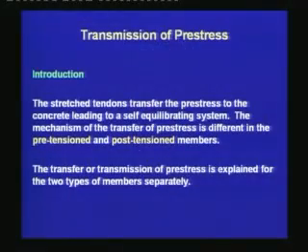In a prestressed member, the prestress is transferred from the steel tendons to the concrete. Now, the mechanism of the transfer of stress from the steel to the concrete is different for a pre-tension member and a post-tension member.